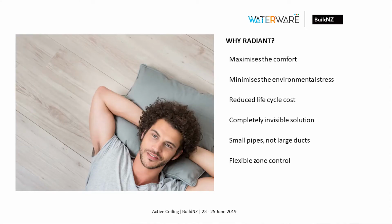So why radiant? Radiant maximizes the comfort in the space. So for the reasons that we've talked about. Number one, because we're working with such a big surface area, the temperature difference which we're working with is very compressed. So in heating mode, if our target temperature is 21 degrees, then our surface temperature will be 25, 26.